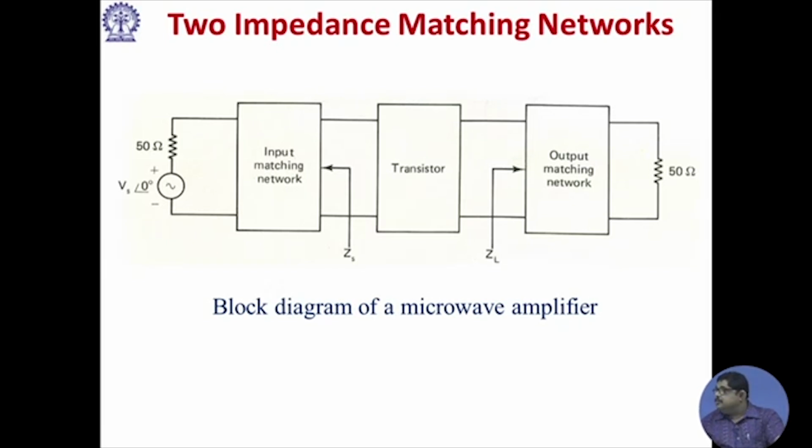Because of the coupling between the input and output, since any transistor is a 3 terminal device, where one of them is common, you need an extra level of matching network. Generally they need 2 matching networks, but we will not talk of this in these lectures. This is for the designer of a microwave amplifier, who should know how to do it; it is a more involved study.